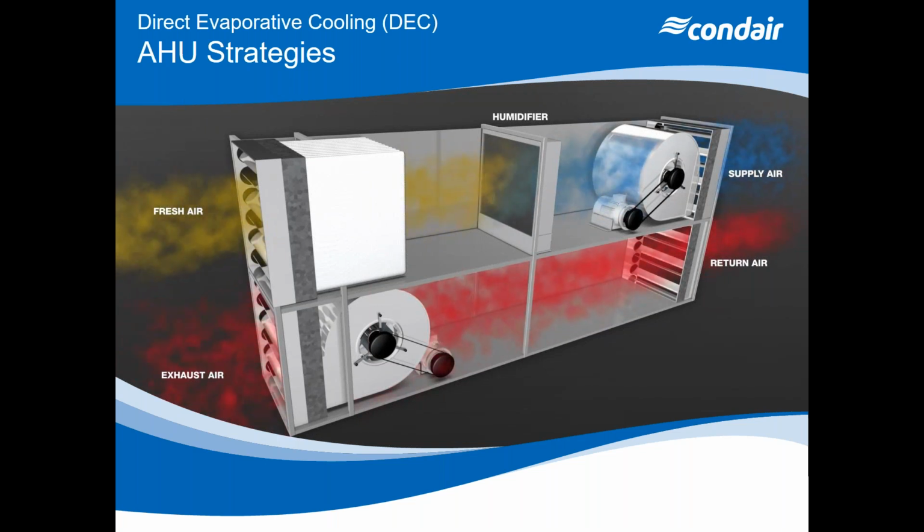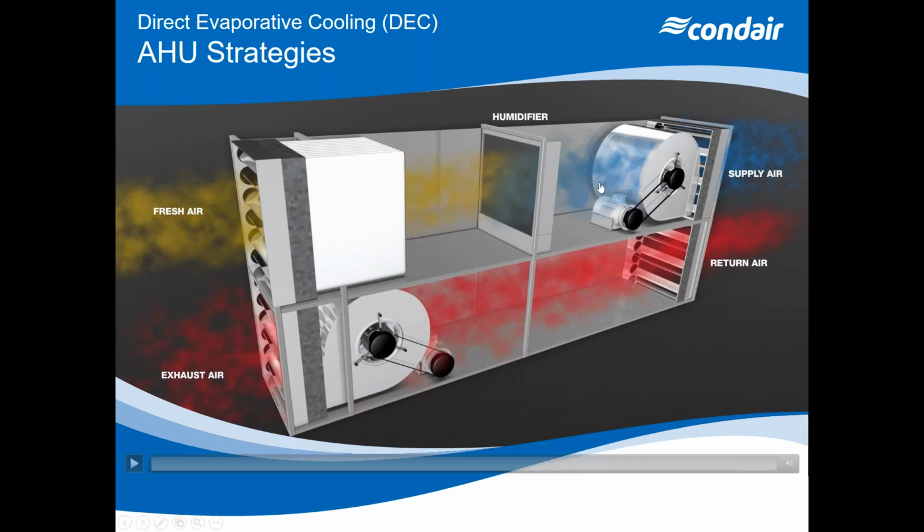So we're cooling the air as we're using that heat energy to evaporate water into the air. So we're then sending that cooled, humidified air into the space. And then return air comes from the space and is just exhausted. It's the most simple form of evaporative cooling. It's purely direct evaporative cooling.